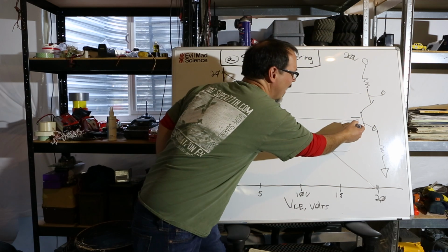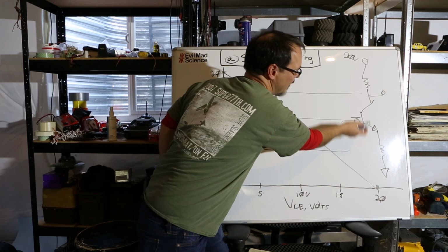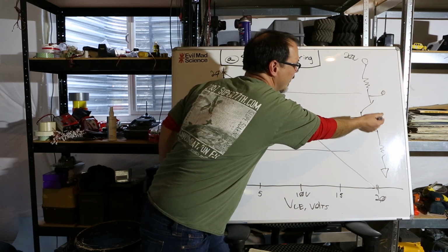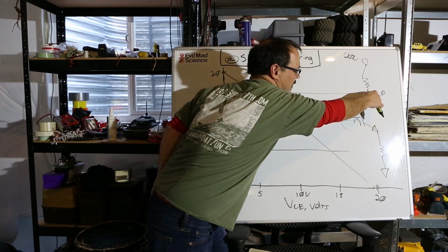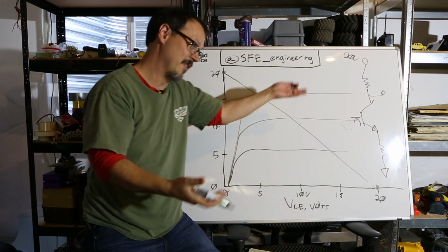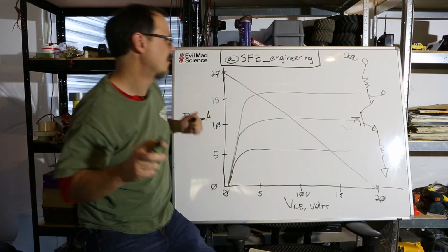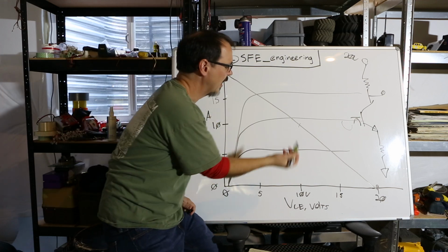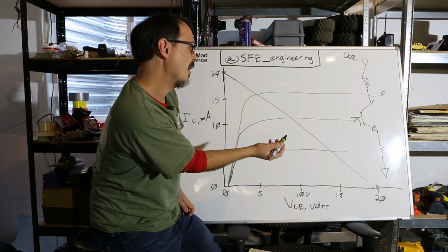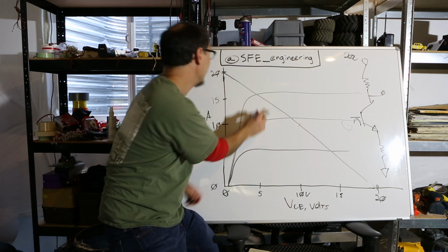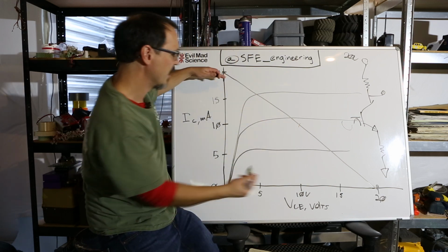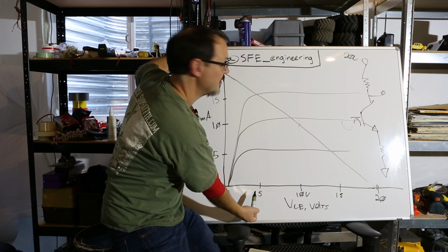Now, same thing, if I've got a high going signal there, it's going to turn this thing on harder. This becomes a smaller resistance, okay? So this voltage actually comes down because that's effectively a voltage divider. So what it's going to do on the load line, when it turns on more, current goes up, this voltage goes down. So your current is rising and your voltage is decreasing.